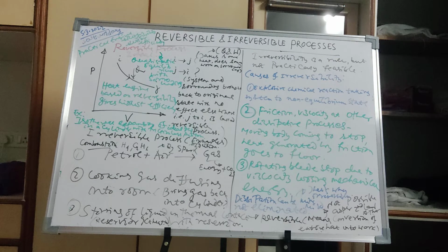In isochoric there is no work done because the volume remains constant. So whatever heat you supply, it increases the internal energy. Okay, then we studied the heat engine, the refrigerator, then the heat pump, and we derived the equation of efficiency of a heat engine and efficiency of a refrigerator, which is otherwise called the coefficient of performance. Till that point, till heat engine and refrigerator, whatever we studied was the first law of thermodynamics.